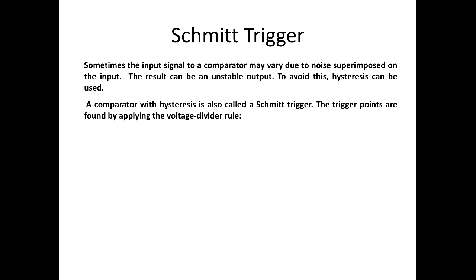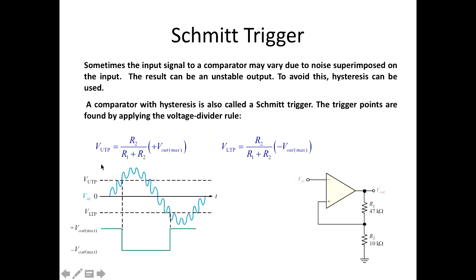It's no point in studying the Schmitt trigger without understanding that. So a Schmitt trigger is a comparator with a hysteresis. The meaning is it doesn't have one level. You are making a band, with a lower cutoff and an upper cutoff. And then you can design a Schmitt trigger, and this is an example of one. In a Schmitt trigger your signal is connected to the inverting input, but then you have a positive feedback. So a Schmitt trigger is something with positive feedback. Then you can create that banding, lower cutoff and upper cutoff, using these two resistances.